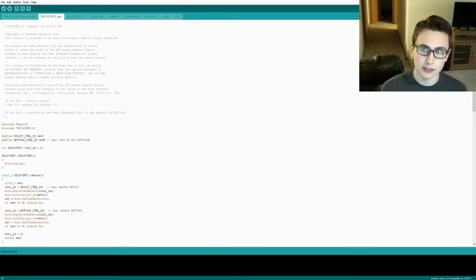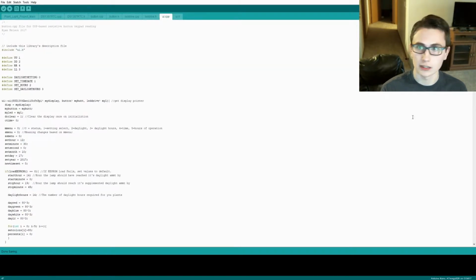Beyond these libraries, I've written some code that handles the inputs to the plant light, namely the enter button, keypad, and photocell. I've also written some code that handles driving the LEDs at a specific current, and turning on the fan when power sent to the LEDs will require active cooling. The remaining code handles the UI, setting menus, and pretty much everything else. Let's start with the highest level, treating all of these classes as a black box.